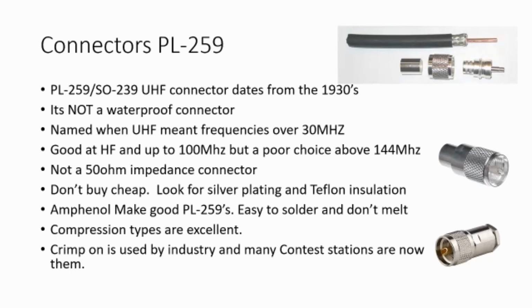There's lots of cheap ones when you go to the rallies. I've even seen fake gold-plated ones, and they probably work fine at HF. I've always tried to stick with good connectors. I've got a couple of examples here that I can show you. If you're looking for good connectors, Amphenol make a good PL259.